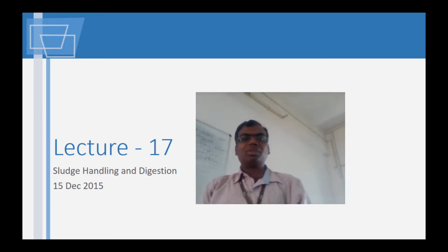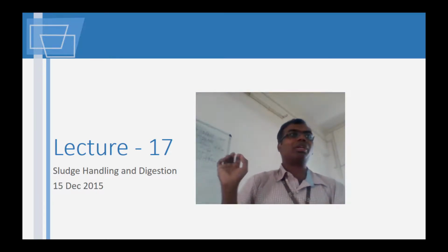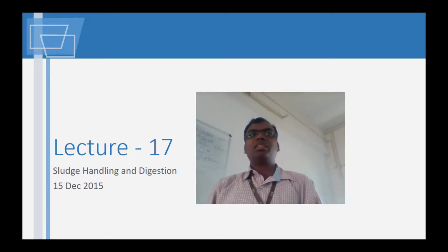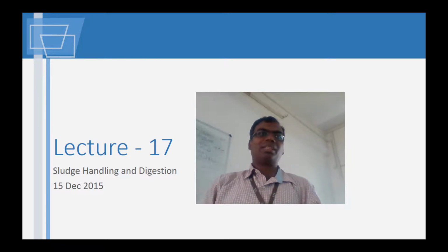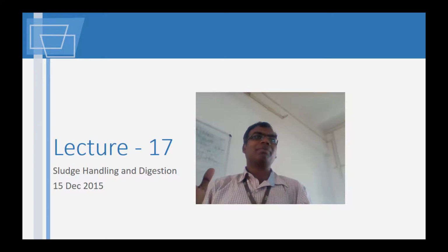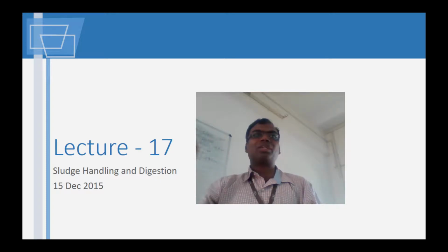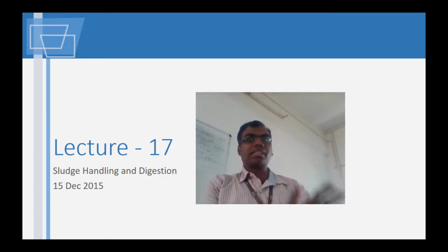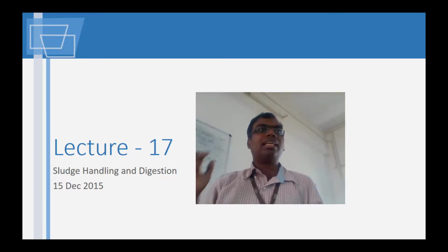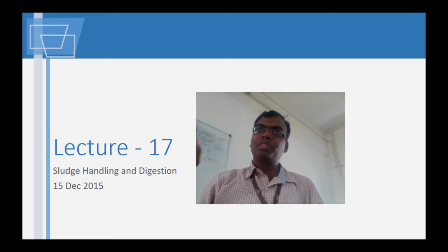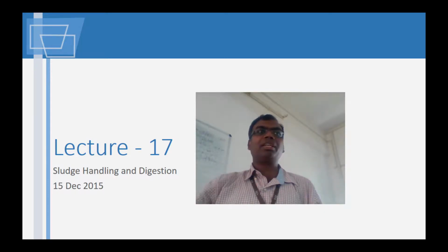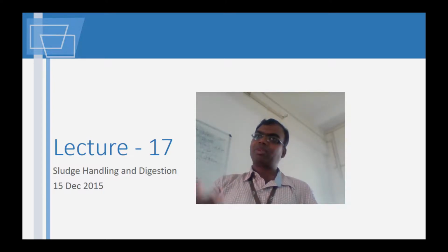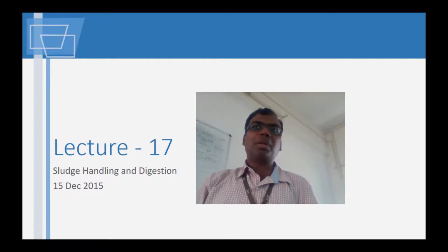Morning friends. So in today's lecture we will have a little bit of an idea of what we do to sludge. The primary treatment results in your influent getting screened of all the big particles. No very big particles, no grit and all such things are removed. Whatever biomass is generated there from the treatment of the screens, that biomass is going to be further treated, and you will be using some method to generate either biogas or other things depending on the requirement of the community or the plant design.